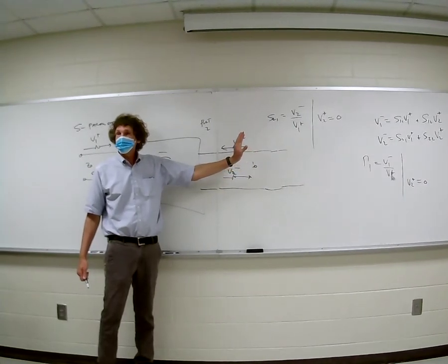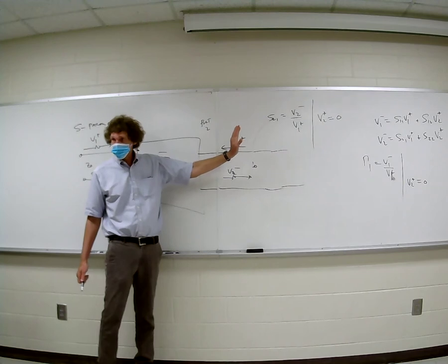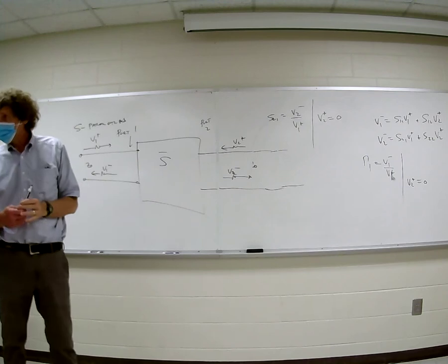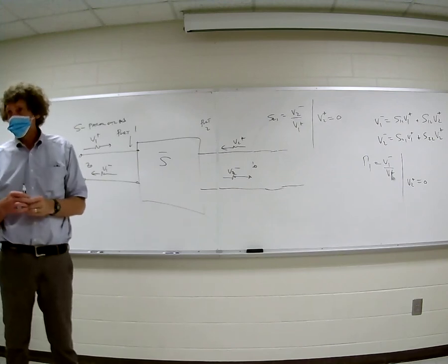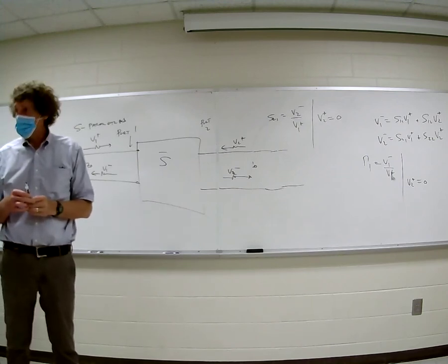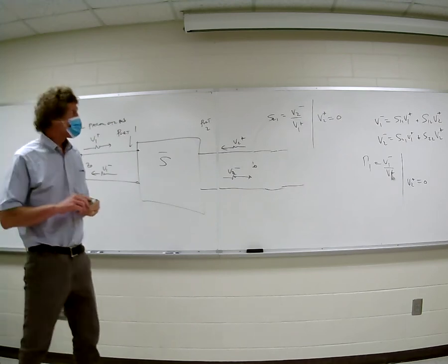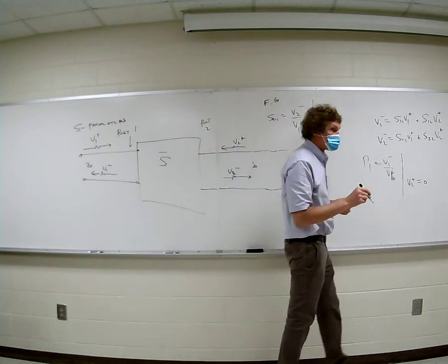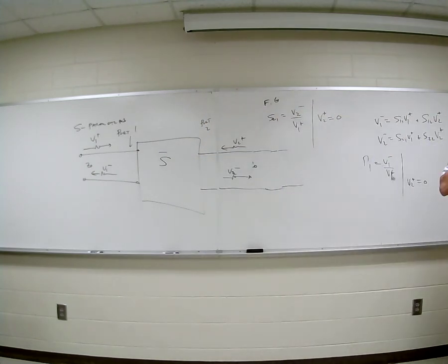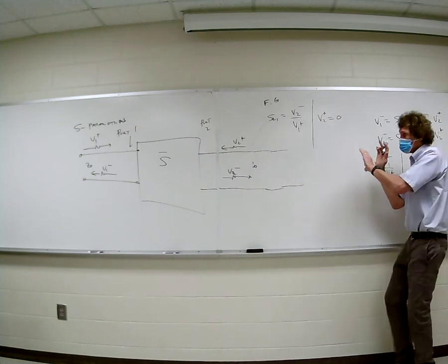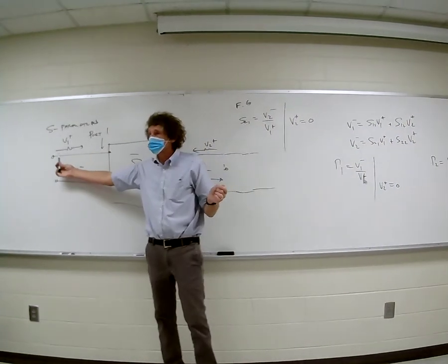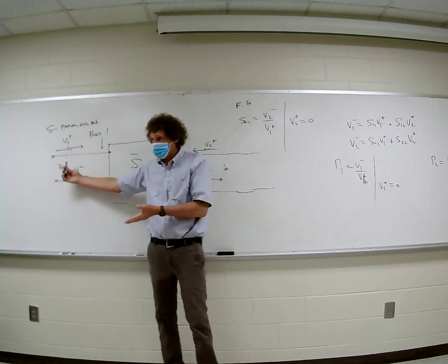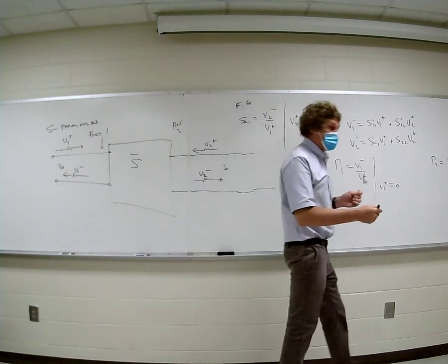Well, the ratio of those two would be called the gain if it was a voltage ratio and you had a voltage amplifier, a standard BJT or an op-amp. You all with me on that? So that's something that makes sense, right? So S21 is like the forward gain. Y'all follow me? Now, if you want the opposite, the reverse gain, like if I put a signal in here, how much signal gets out here? The gain is a loose term. It probably decreases the value, but they call it the reverse gain.